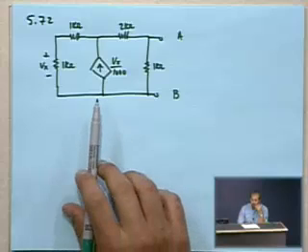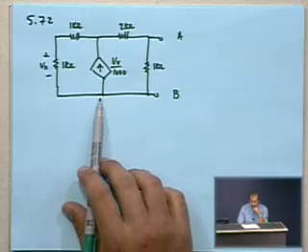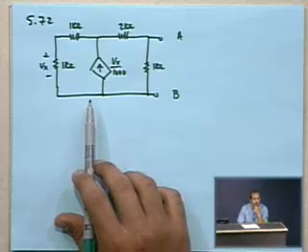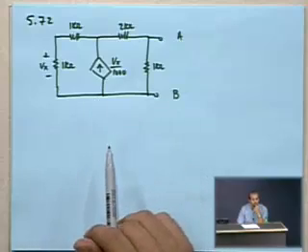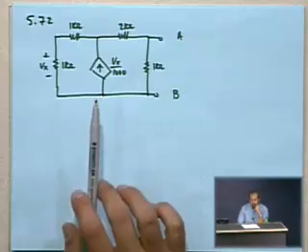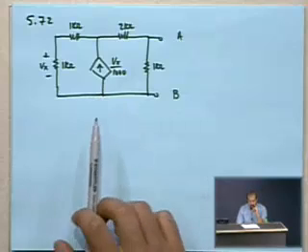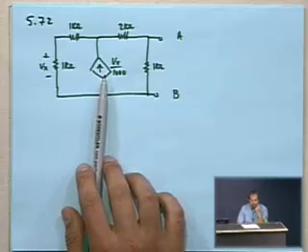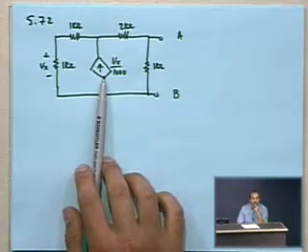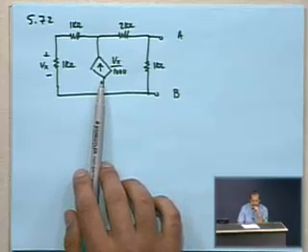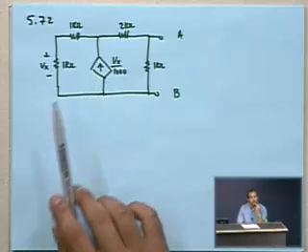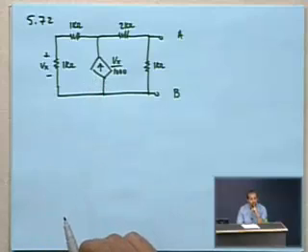So with the circuit that contains only dependent sources, we'll hook up a test source of some kind, whether that's a voltage source or a current source. Again, that's up to you which one you'd want to do. When I look at this particular problem, I see this current source in the middle, and I don't like the idea of needing to deal with some sort of supermesh or loop analysis to solve for the current there. That sounds pretty nasty to me. So I would really rather do a nodal analysis on this one.